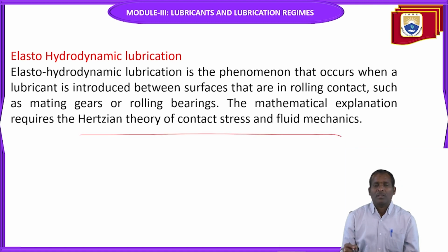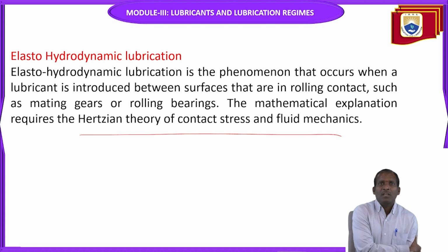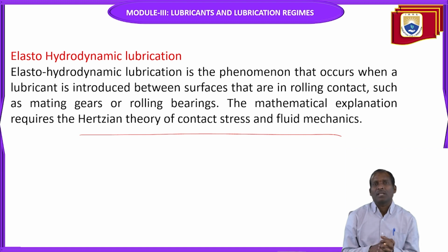According to this theory, you can define this system elaborately. Whenever two mating gears or rolling bearings are in a contacting position, due to the elasticity property of the material, there is a lubricant introduced between these two surfaces. That's why this type of lubrication system is called elasto-hydrodynamic lubrication.